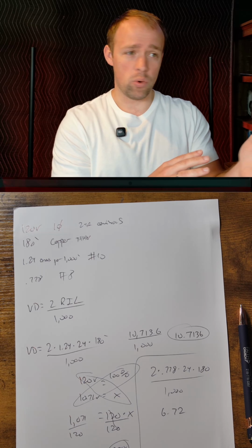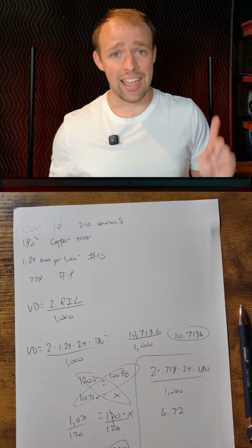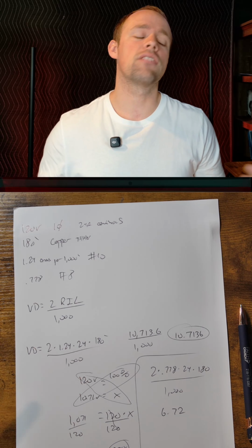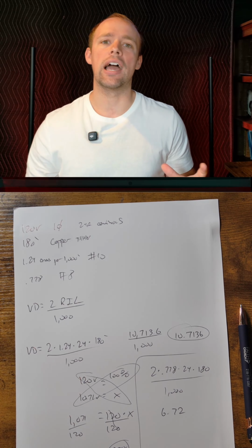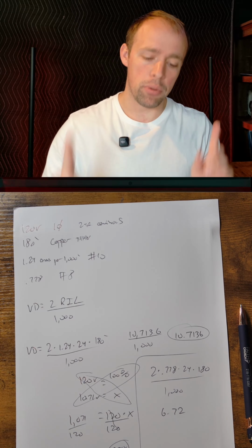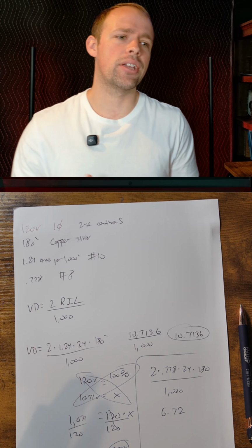The question wasn't asking to size the conductors. In fact, it gave us the conductor size. It's asking for the voltage drop. We do not apply 125% when trying to calculate the voltage drop.